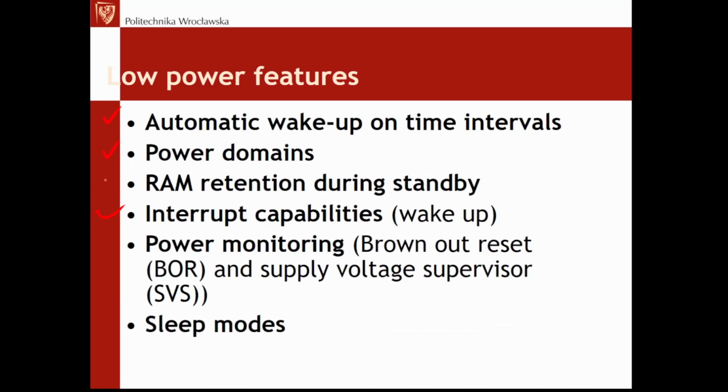Then another important low power feature, which is today a must, in fact, is the retention of RAM during standby. It means that we can switch off the microcontroller and the peripherals, but the RAM should stay supplied. We talk about, of course, the SRAM, so the registers, in other words.